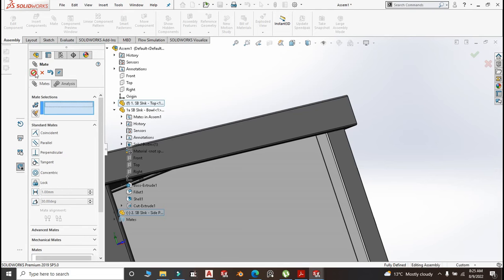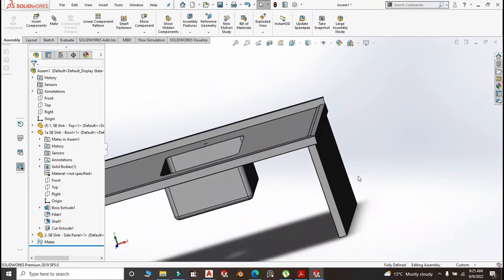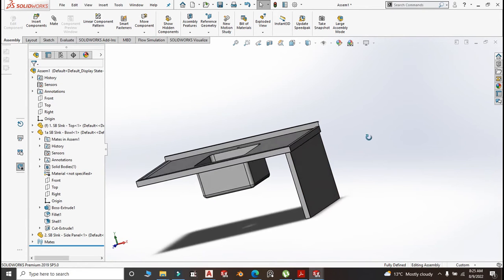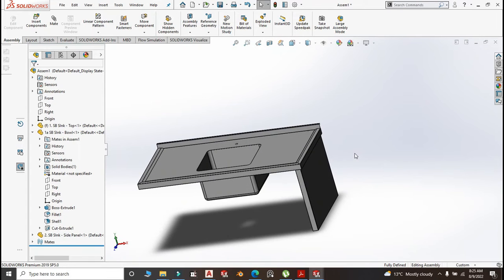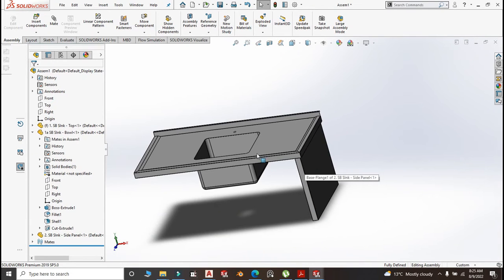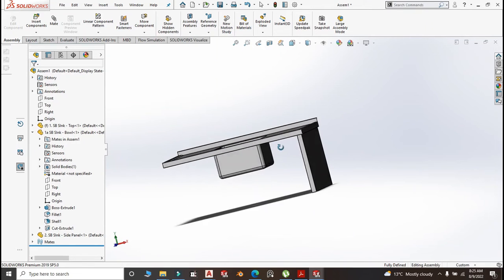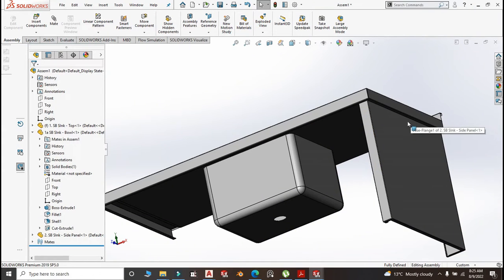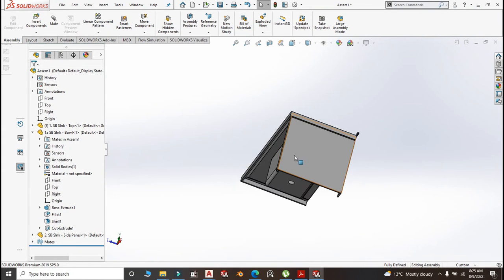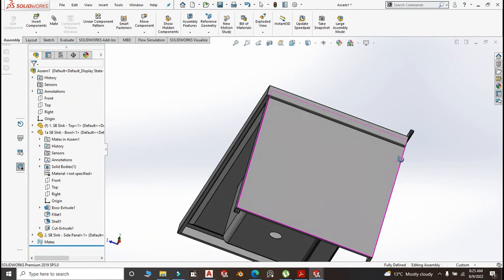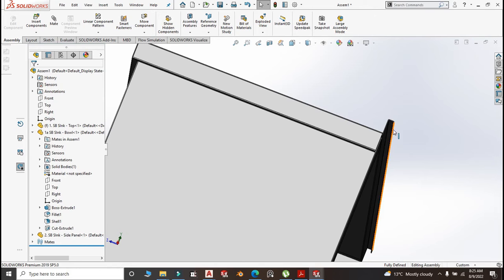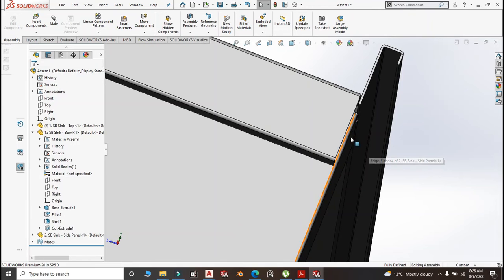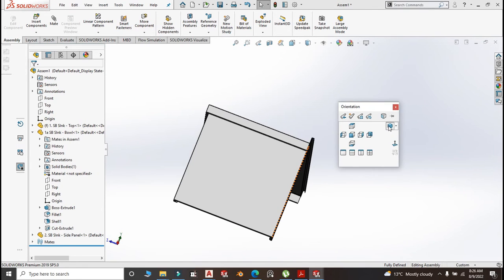Yes, that's good. Now for those who were wondering why we were deducting 30 millimeter from the overall size of the undershelf, it is because the sink is 1500, and remember we have an edge flange here of 15 millimeter and another edge flange here of 15 millimeter. Same applies to the side. We have 15 millimeter here and we have 15 millimeter here, right? So that your side panel flushes with the back side